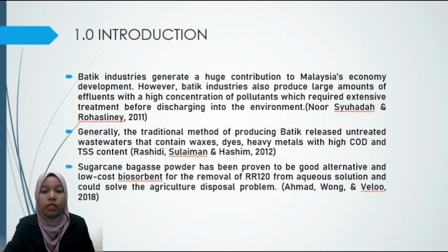Batik industry is known as one of the largest industries that contribute to Malaysia's economy. However, this industry also produces wastewater with high concentration of pollutants which need an extensive treatment before it can be discharged to the environment. So basically, this wastewater contains pollutants such as waxes, dyes, heavy metals with high COD and TSS contents. For the treatment of this wastewater, sugarcane bagasse powder has been proven to be a good alternative and a low-cost bioadsorbent to remove RR120 color.